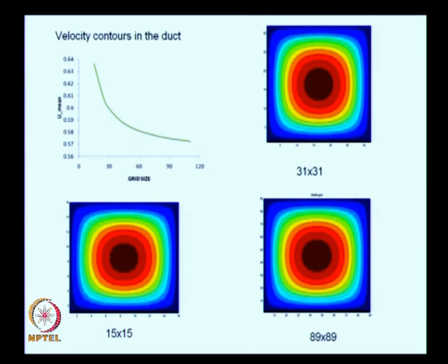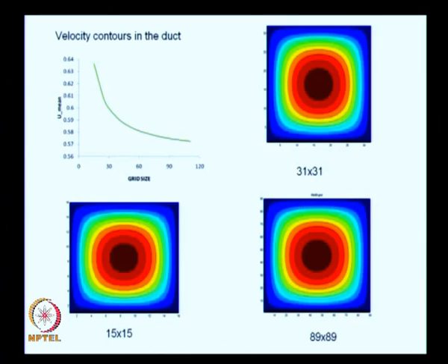So this illustrates the power of computational fluid dynamics, that we can now get a velocity variation within the cross section by having a large number of grid points spread throughout, and we can use fairly simple methods which are very easy to program on the computer and which are therefore easy to solve, and then get the velocity distribution for this fairly complicated shape under steady conditions.